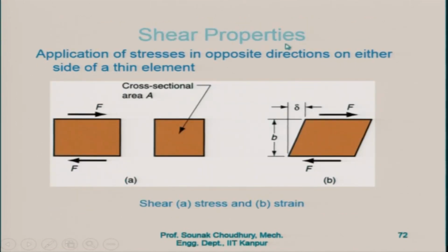Shear properties. Now, this is the application of stresses in opposite directions on either side of a thin element. Suppose this is a thin element and some stresses are applied, let us say this is the shear force. This will apply shear stress on the initial material and the material will be deformed in this way, where this is the height and this much is the deformed part.